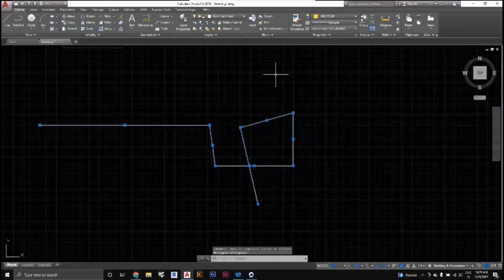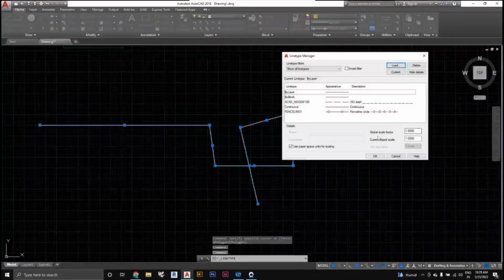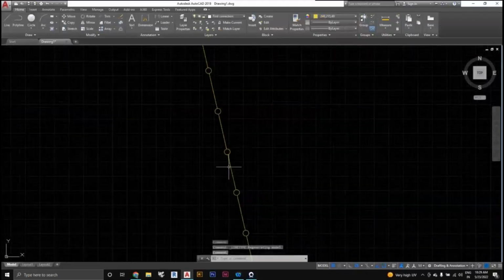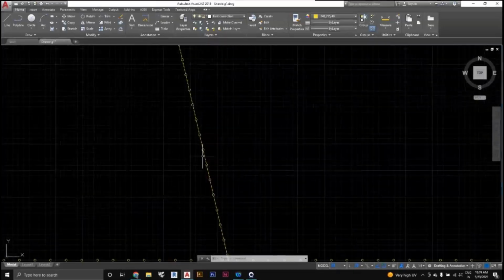This is because of the scale of the line that is being used. Okay, so if I select it again, then go to others, there is an option here called global scale factors. You could change this now to something like 5 and give OK. Again it is small. If you zoom in, you will understand it is really small.